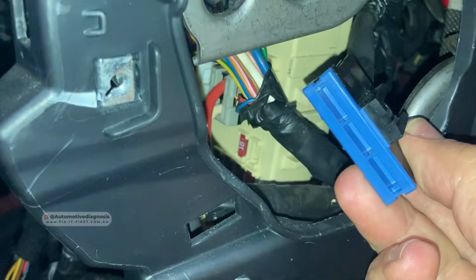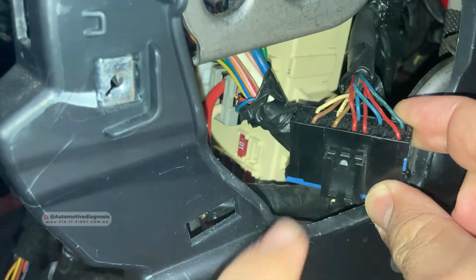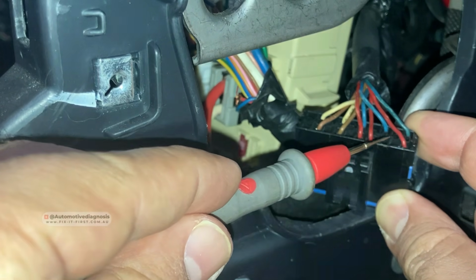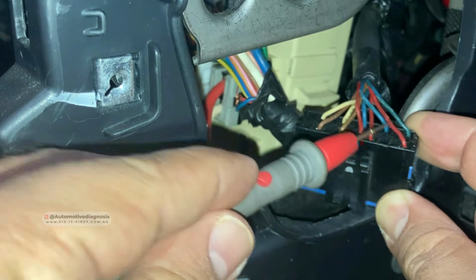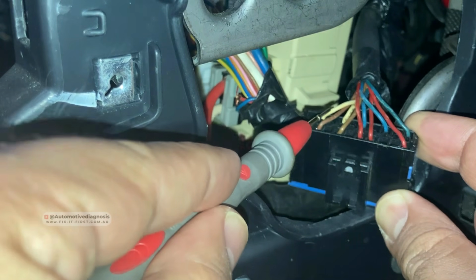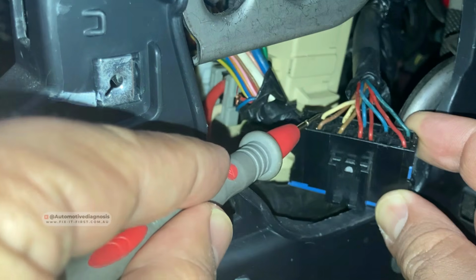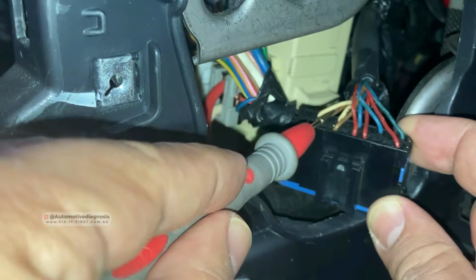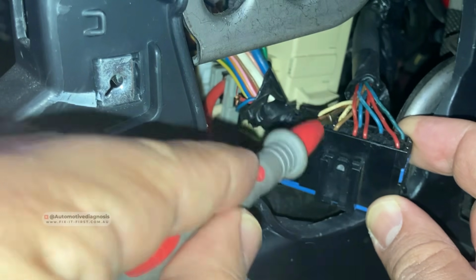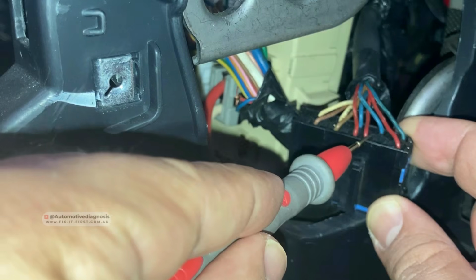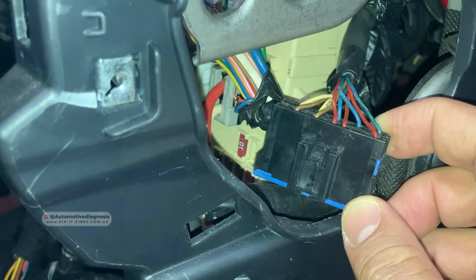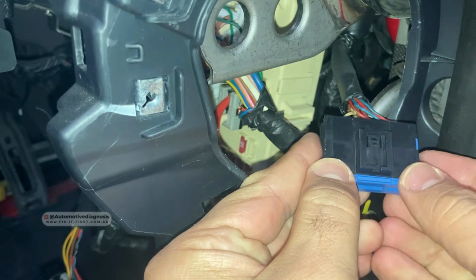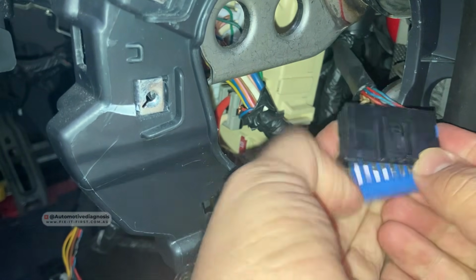So you see the joint connector, and at the back, if you look at the wirings, red and blue wires, they are for the high-speed CAN. So this is CAN high and CAN low, they are on the high-speed CAN. And these white and brown wires, they are for the low-speed CAN or B CAN that you saw on the diagram earlier. So this joint connector is gonna connect the network together. So these two are connected to each other, these are connected to each other through the joint connector. And for isolating the problem area, we can actually use this joint connector. So if I take the joint connector out, you should do this very carefully.